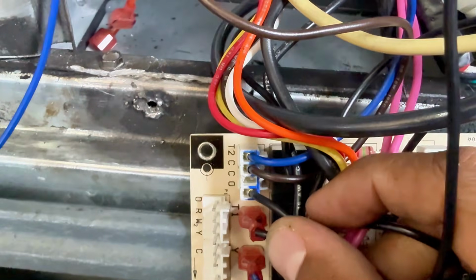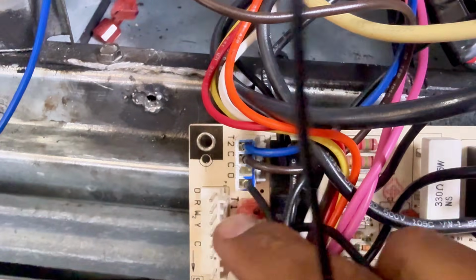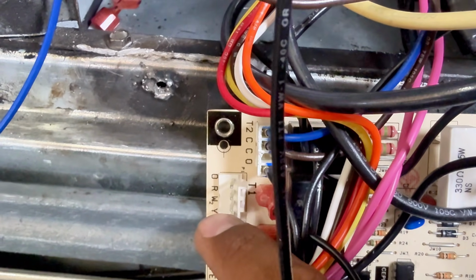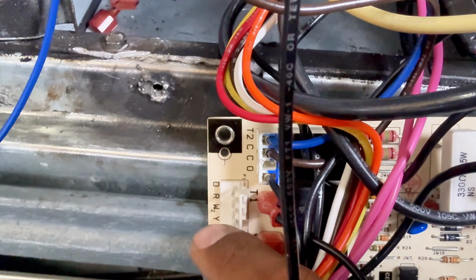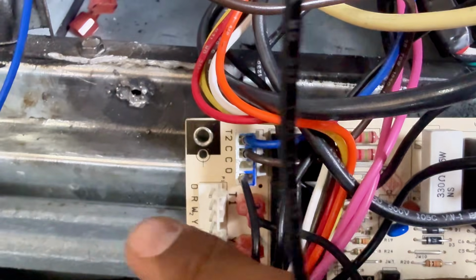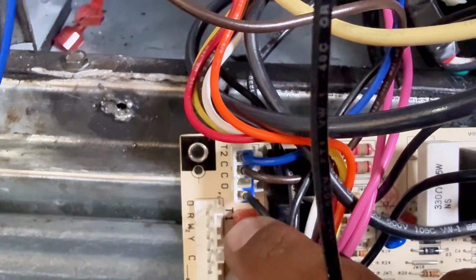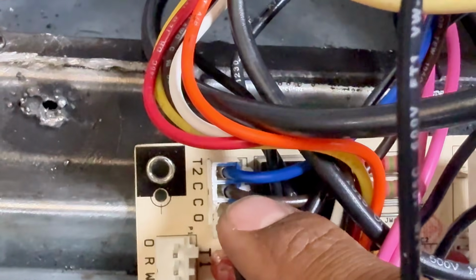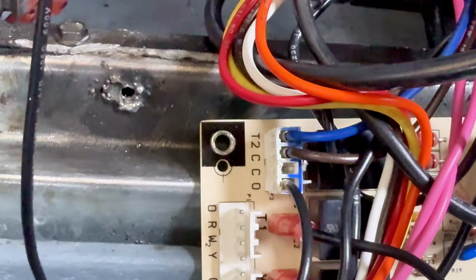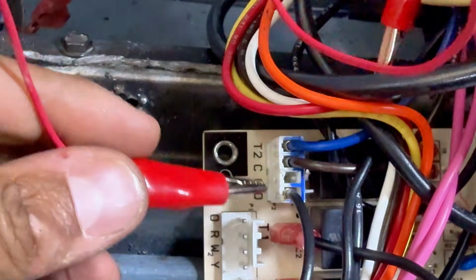And this black one goes to my, let's get a little bit closer, there we go, T1. Once T1 gets 24 volts, because like I said, it comes out from Y from the other board, it gets 24 volts. Then it goes here, and then it goes through my pressure switches. Then it comes back on black. This is what the board does. It then sends from T1 internally. I know you can't see it, but internally, just imagine an alligator clip, right?